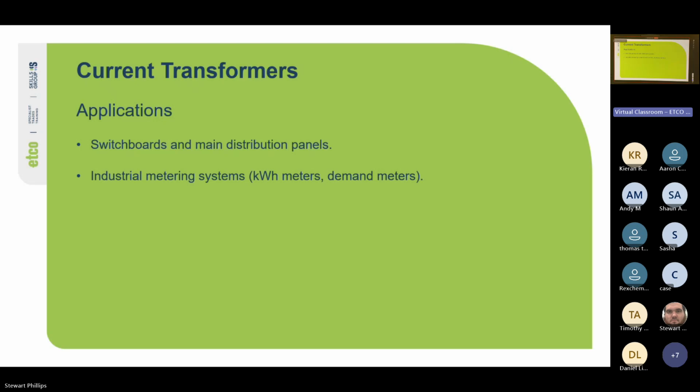Obviously, if you've got current flowing into an industrial site, it's going to be many magnitudes higher than a residential installation, so your standard kilowatt hour meter cannot handle it. And believe it or not, they use the exact same meters that you use in domestic as they do in industrial. They just hook up CTs to the mains to more accurately monitor the current safely.